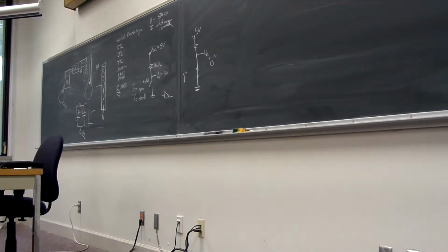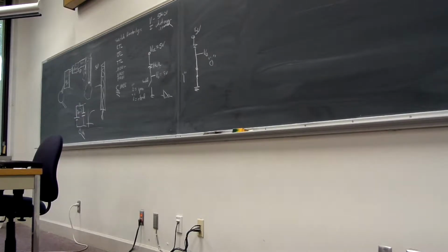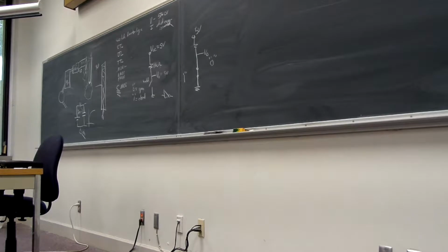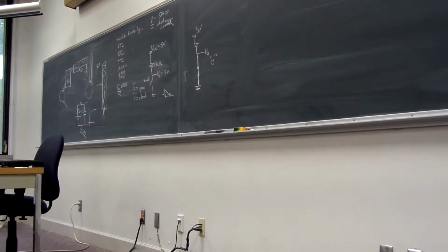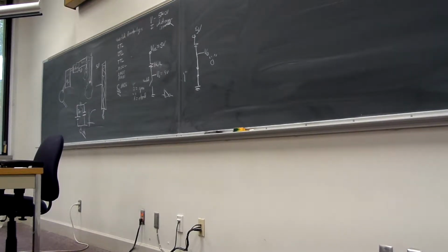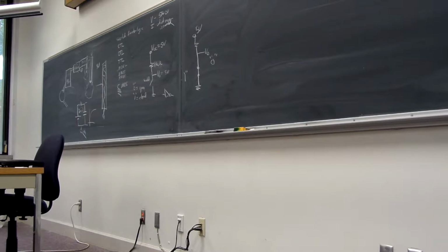Do you suppose a switch really has absolutely 0 resistance? Not unless you've got it cryogenically cooled down to a few degrees Kelvin. Okay, there's resistance associated with it. So if I told you that the switch had 4 milliohms worth of resistance, has anything altered? What are you getting out in this case?